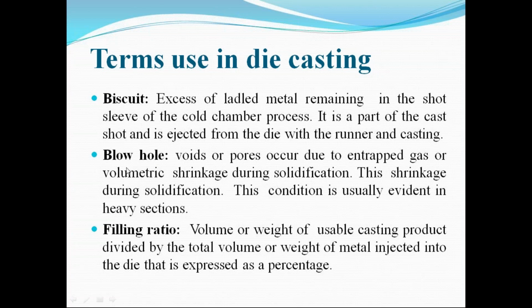Now the next one is blowhole. I already talked about this many times. Blowholes are voids or pores that occur due to entrapped gas or volumetric shrinkage during solidification. This shrinkage condition is usually evident in heavy sections, where the section thickness is very high.